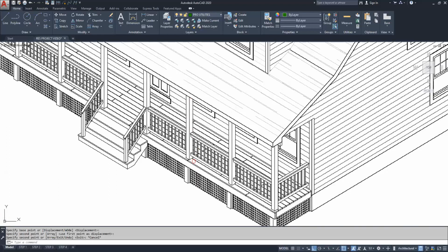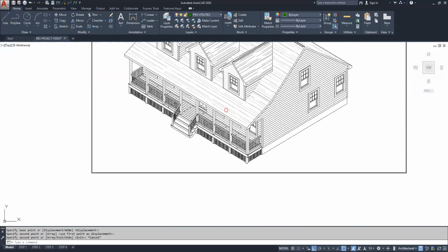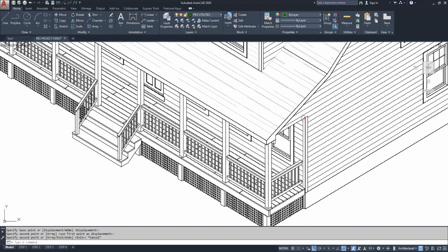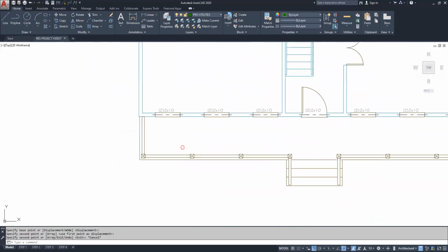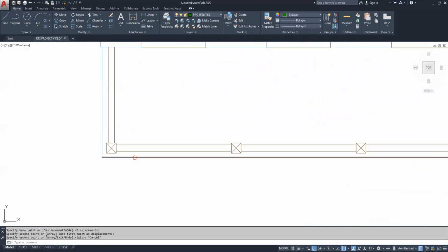You're seeing the studs or the wood posts along the side, and then the header coming across. And that's carrying the weight of the roof and the ceiling inside the porch. The ceiling right here and the roof of the porch is being supported by this bridge from this post to this post. How do you represent that on the floor plan?